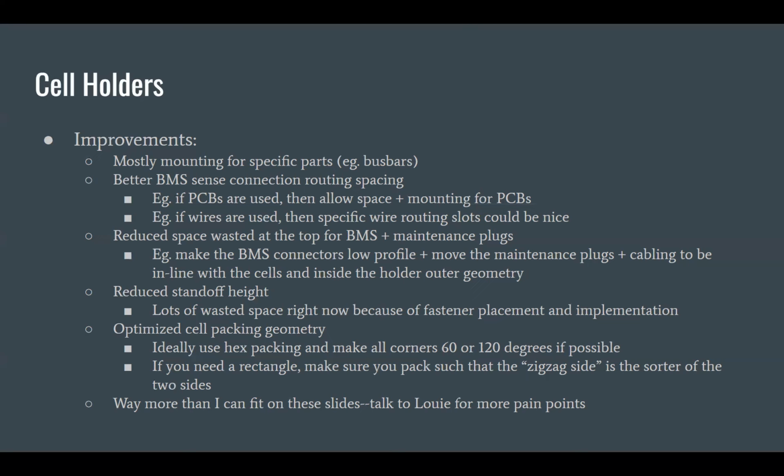That only really matters if you're trying to do a rectangularly shaped battery with hex packing and it's very long and skinny, but that's something that most battery packs end up being. So this does end up having quite a bit of effect. Ideally for future battery pack designs, if they do end up being longer and skinnier and using hex packing, we would abuse that property. You basically only have the zigzaggy bits on the ends, and you're able to do flat faces on both sides, because then you can get more cells in a smaller space.